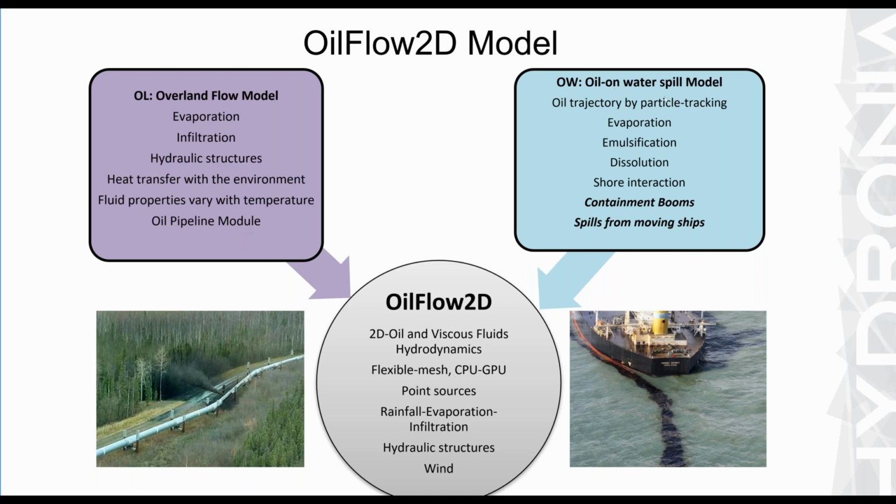Now, the oil and water spill model can simulate the trajectory of the oil by particle tracking, and also deals with evaporation, emulsification, dissolution, and shore interaction. And we recently added two new components to this model, which are the containment booms and oil spills from moving ships.